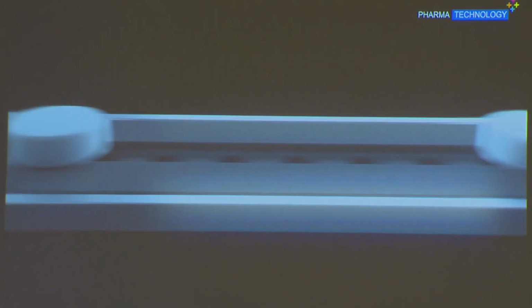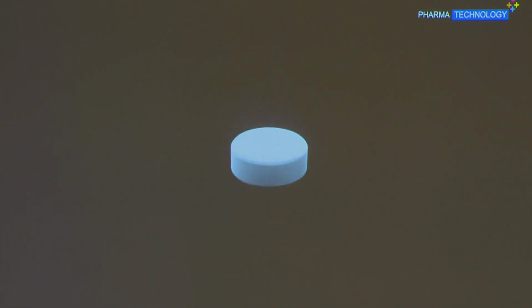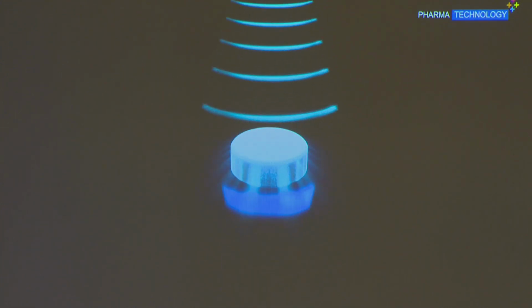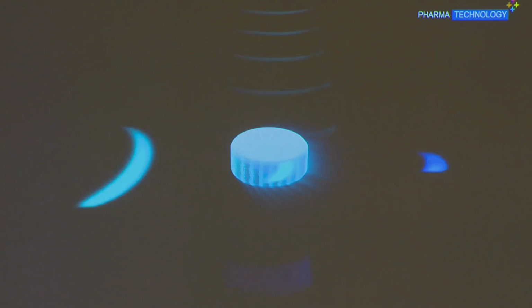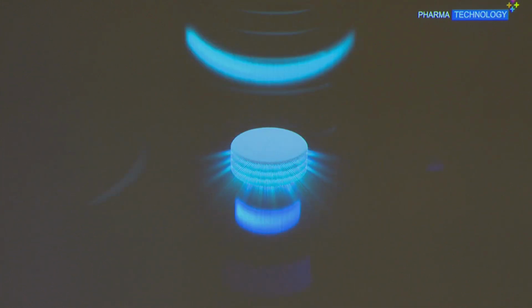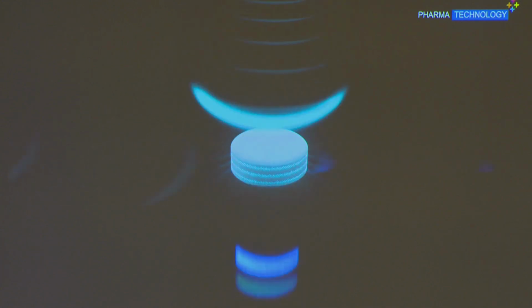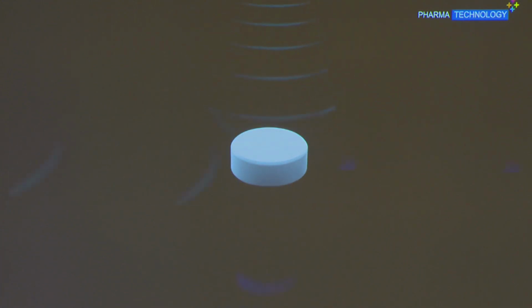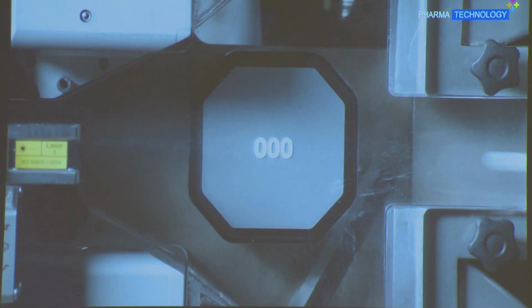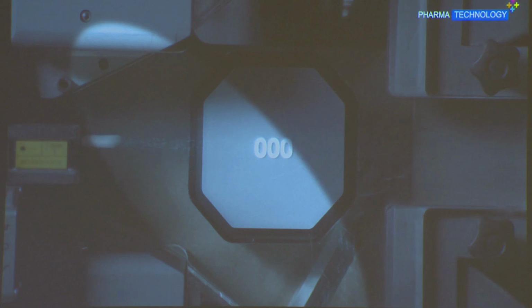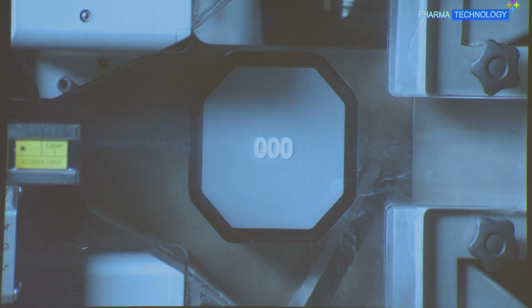After the API's fraction measurement, the tablet instantly enters the 3D microwave resonator. Inside the cavity, 3 microwaves are continuously emitted in orthogonal directions. Every tablet passing through the sensor modifies these 3 microwaves depending on their mass. Directly after the mass measurement, out-of-specification tablets are removed, while correct ones are transferred into the conform product bin by the fast reject gate. In addition, a rejection confirmation sensor guarantees that non-conform products are correctly discarded.